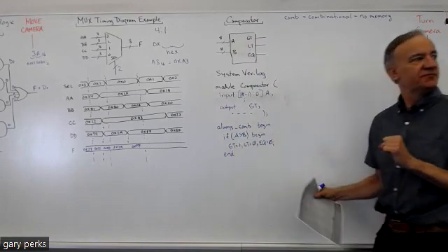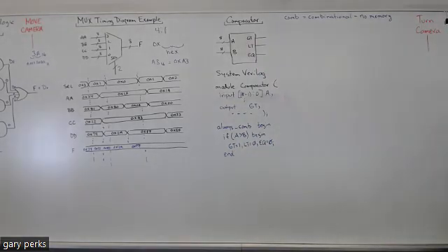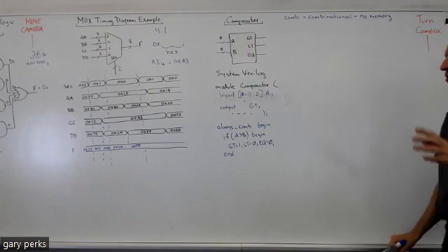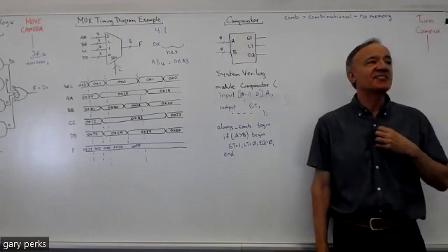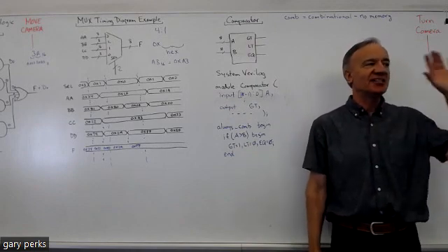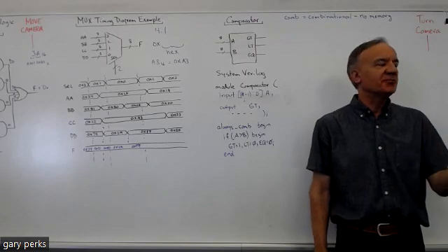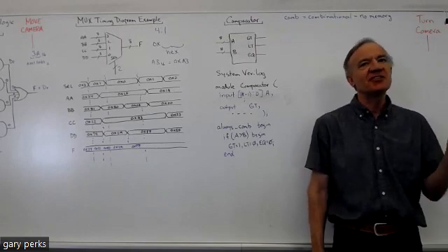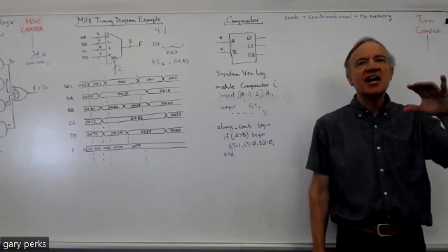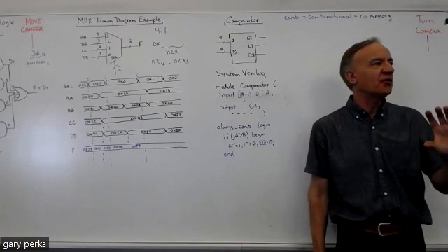But do we not need to say assign for an if statement? No. That's one of the things that's different. Within this always_comb, in fact, if you do put in assign, you'll get an error. I'm glad you asked that question, because that's a common thing. You cannot have assign statements within an always block.